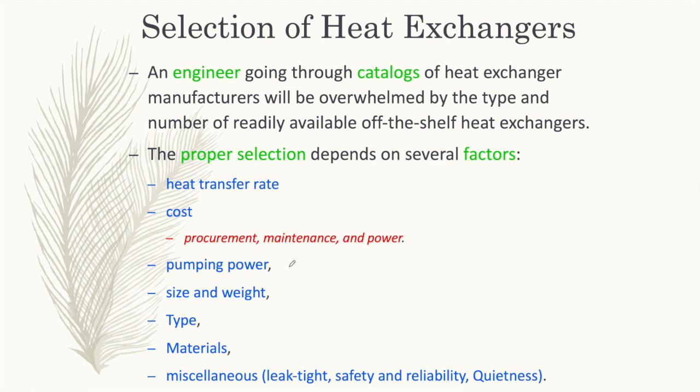Do not choose a compact heat exchanger, because it is not suitable. It must also depend on other factors, for example types, materials, and miscellaneous factors, for example leak type, safety and reliability, and quietness. Those are all the factors in order for you to select the heat exchanger. Okay, thank you.